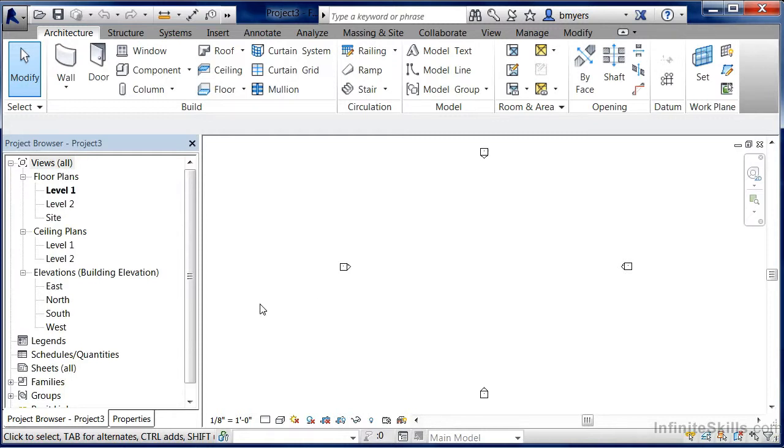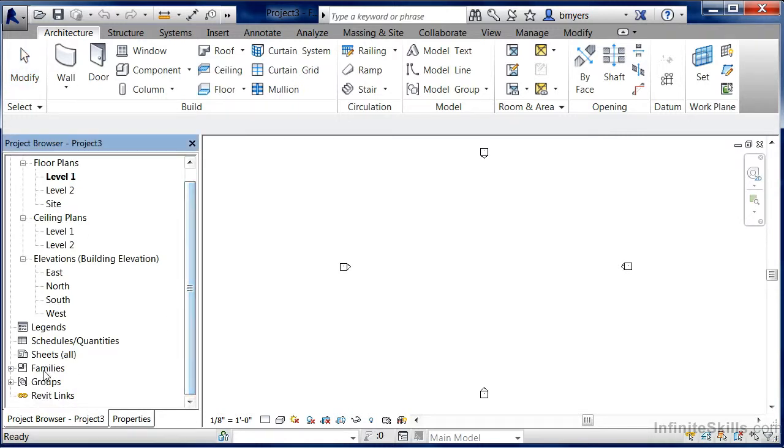Some of the settings that are going to be in there are default floor plan views, default ceiling plan views, or default elevation views. Anything that would have a schedule associated with it could be preset by default, so the second you start to draw those things in, the schedule will start to populate. You can also load in default families, such as your default walls, doors, windows. The kinds of items you'd like to have from project to project, they can just be in your template. And then when it comes time to start a project, there they are.